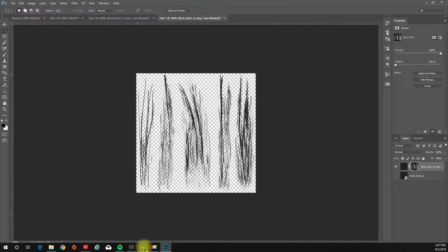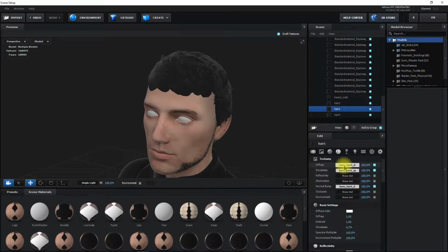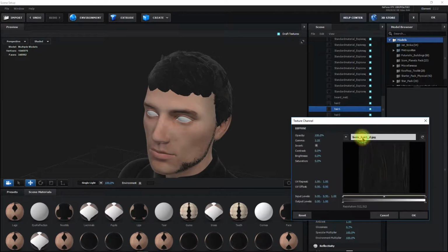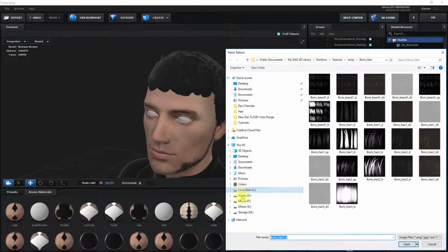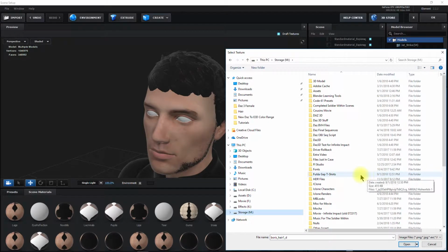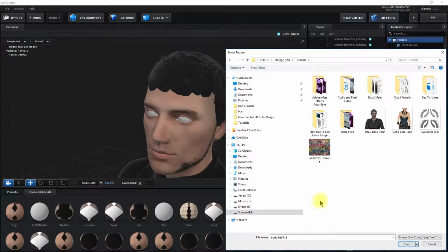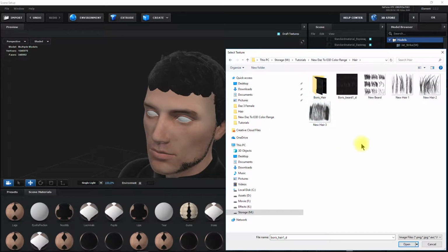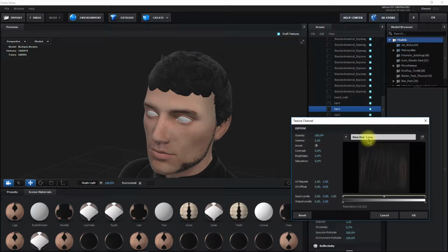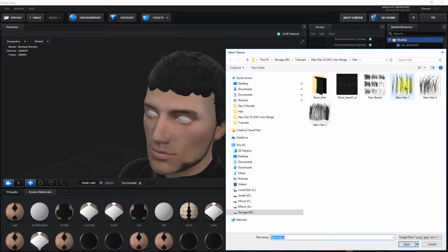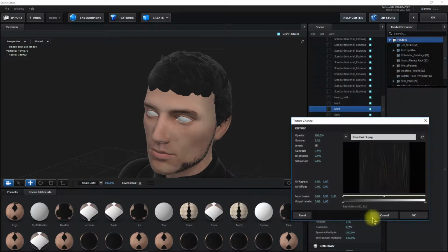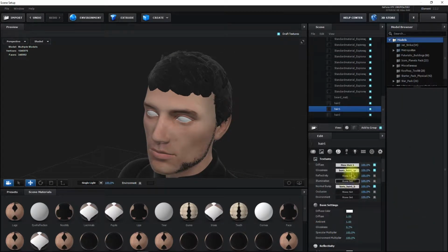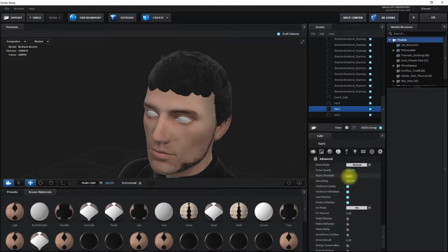Jump over to After Effects and replace the diffuse texture. You notice we're not worried about any bump maps or gloss. There's no reason to change those. It doesn't have any effect. So on the hair, I mean, it has an effect on the hair and the way things look, but it doesn't prevent us from getting the look we want. So put in the new hair, select the cogwheel, go to alpha threshold, and pull the alpha back.